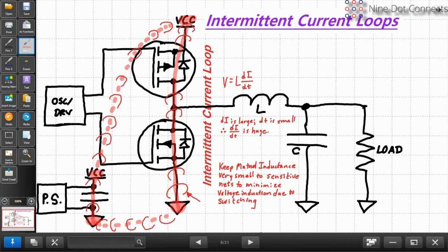I also have another question as to whether all MOSFETs have a body diode. All common power MOSFETs that I see today do have body diodes. Some of the very older ones didn't make them with very good diodes, and some of the other types of FETs don't necessarily have an intrinsic body diode. But all the classic power MOSFETs that you'll look at today, without hardly an exception, you'll find do have body diodes. The characteristics of that body diode change somewhat from transistor to transistor, so you'll really want to make sure you take a look at that if you're going to be relying on it. You wouldn't want to be, say, switching 50 amps and have a diode that can't take a spike at 50 amps. So, okay, continuing on.